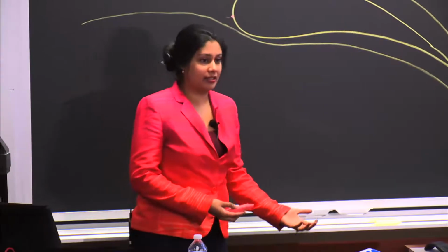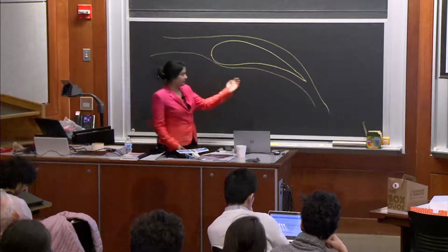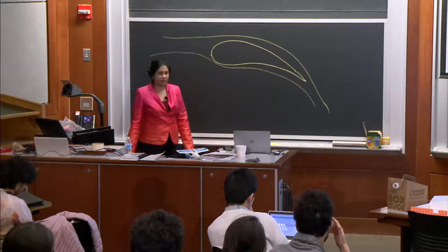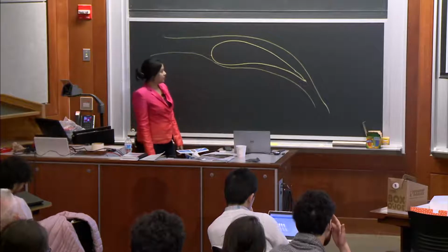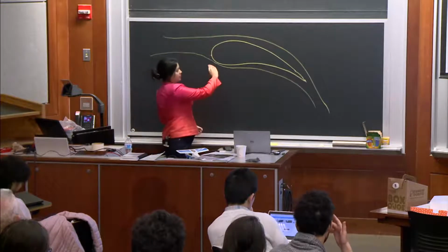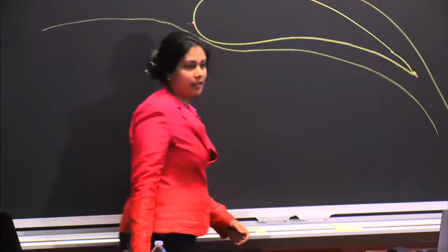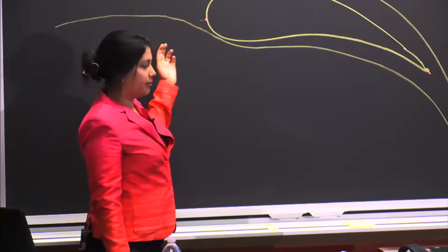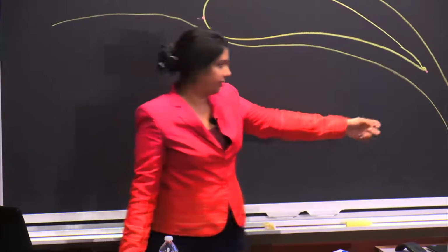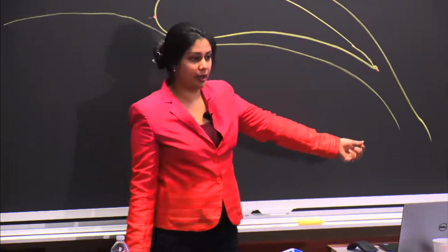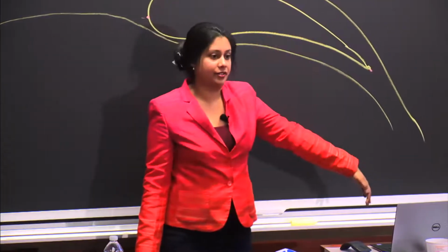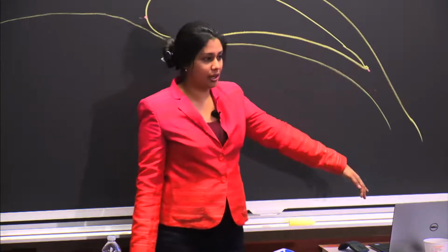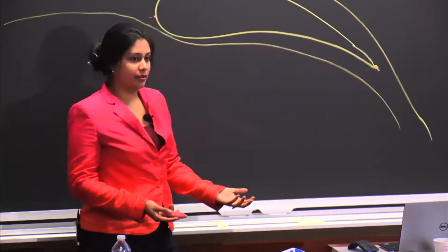But in this false theory, equal transit theory, they say that you have to reach the end at the same time. They also say that there is more distance to cover over the top because of the shape of the airfoil. So in order for the molecules going over the top to arrive at the same time as the molecules over the bottom, they have to go faster. And since the air is moving faster over the top than the bottom, that's what creates lift.